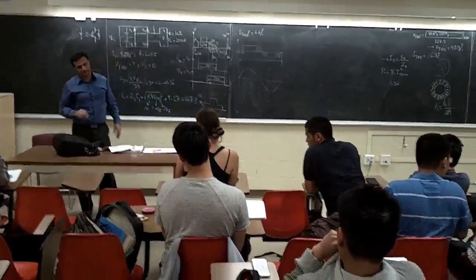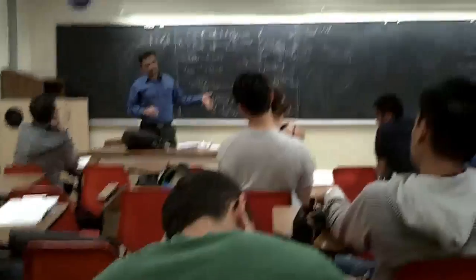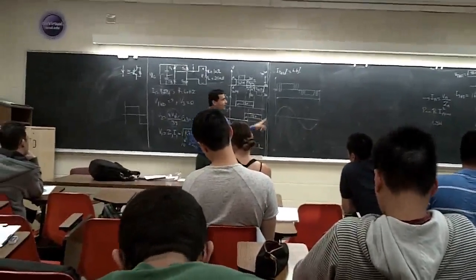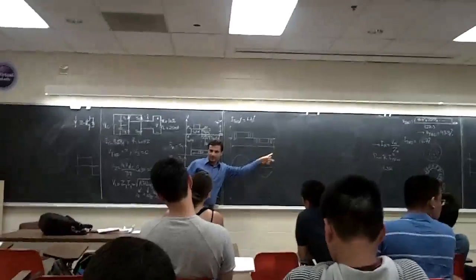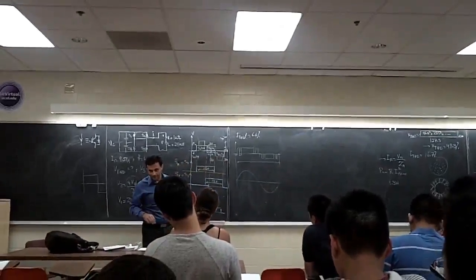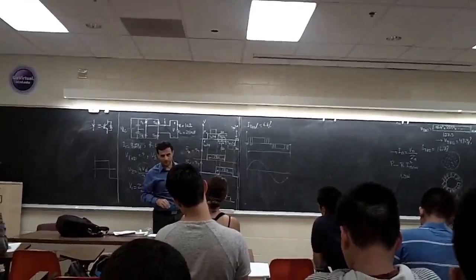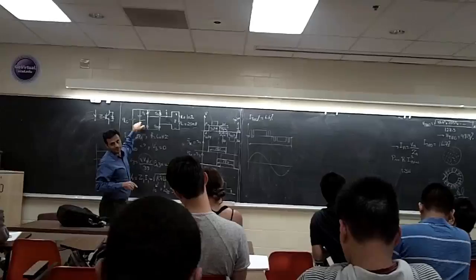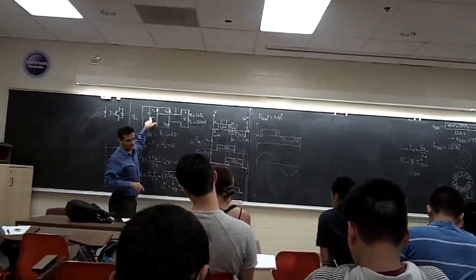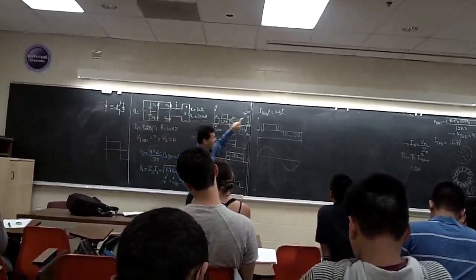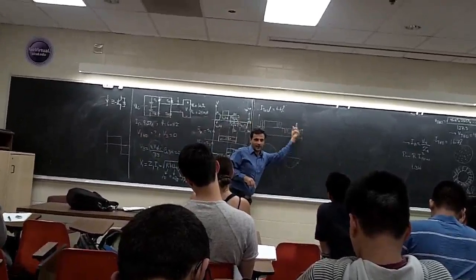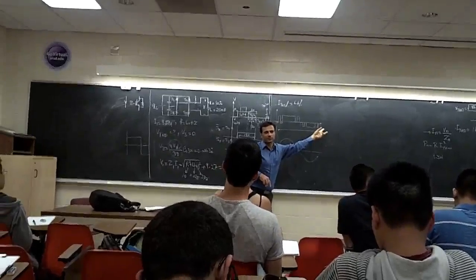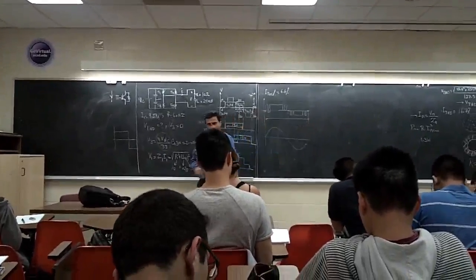When it comes to switching loss, which one has more? With a multi-level converter, there are 2 ways: either you can build it this way or this way. This way has more switching, this way has more levels, right? There's always a compromise here. Which one is better? Do you want more levels and deal with the effort to balance this one, or do you want to go with higher switching and deal with higher loss and those kinds of things? These are design choices. Every project is different.